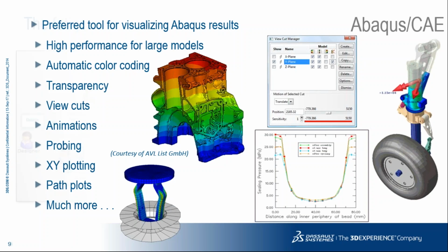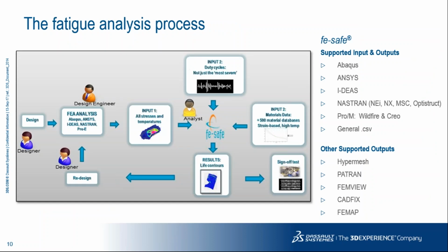The second tool which I was discussing is a fatigue analysis tool, which is used to predict the life of the component, or the durability of that particular component. This workflow explains how it works. It will take the output database file from the CAE, the material will be added, and the load data or road load data will be applied, and then it is further analyzed based on the stress approach or the strain based approach to get the results.